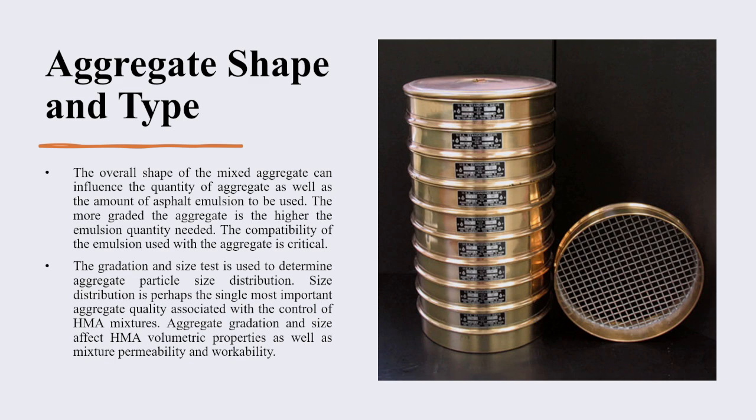What is the sieve? Is it still number 4? No, 4.75 plus coarse, that is for concrete or aggregate in the concrete business. But for geotechnical business, it's sieve number 200.